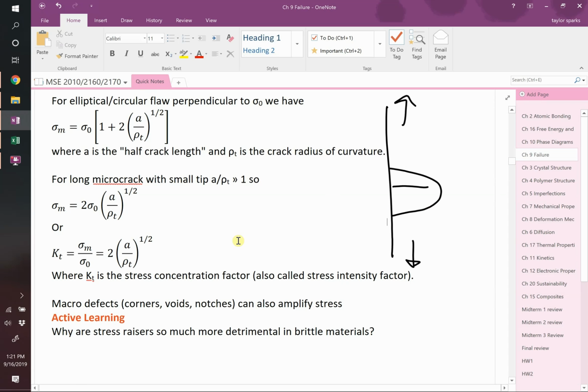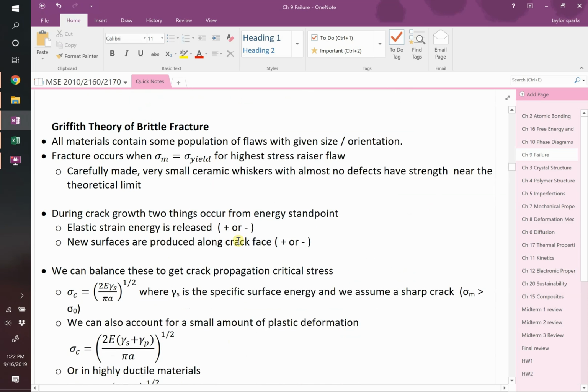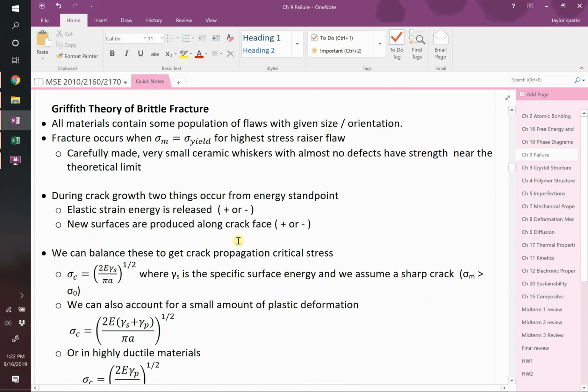Okay, let's keep going. What was really clever about Griffith's fracture theory is that he said, all right, anytime you make a material, these flaws are present. On the surface, in the bulk, you can't avoid them. You can statistically try and describe them, but if you make a big enough sample, it will have a flaw in it. Or in other words, if you have a small sample, it has some number of flaws in it, because they're typically large numbers.